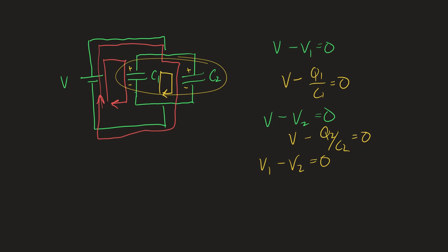Is it clear to you in this circuit that both capacitors have to be at the same voltage? Is that clear to you? All right. The voltage supply doesn't know what's connected to it. The voltage supply doesn't know there's 2 capacitors there. The voltage supply merely provides a potential difference to the circuit, and will push charges to meet the demands of the circuit.